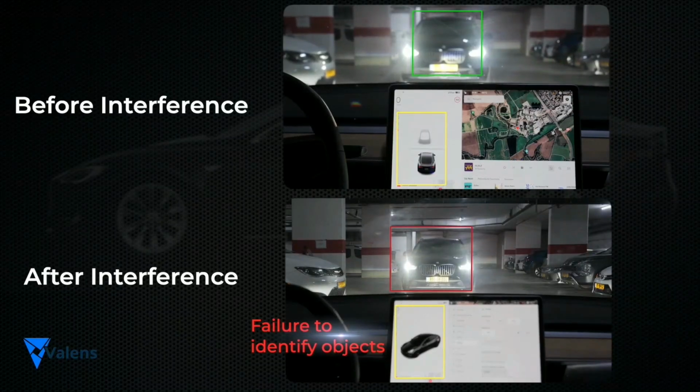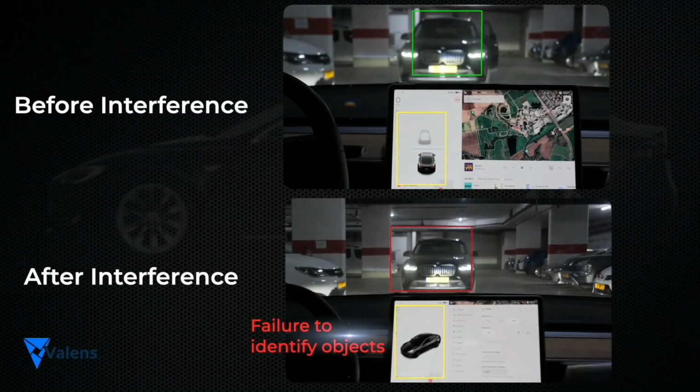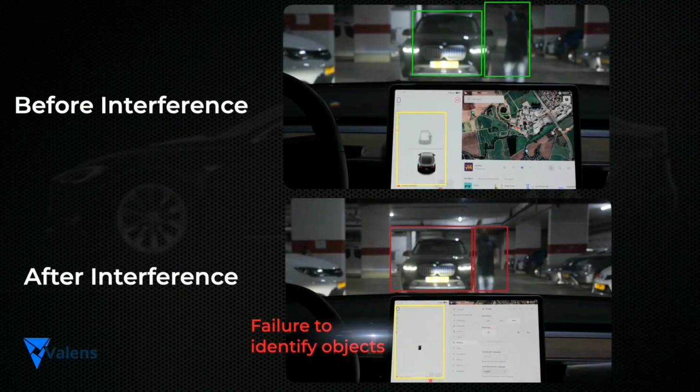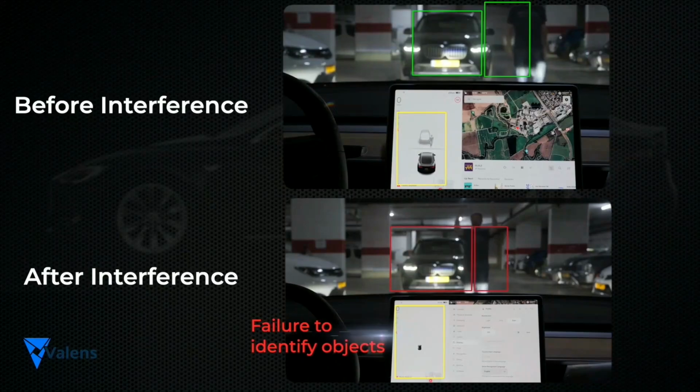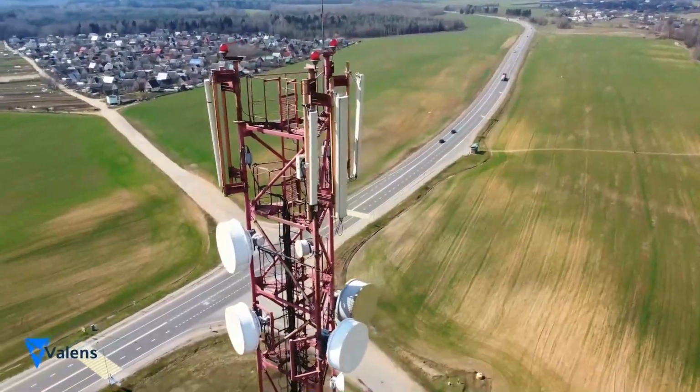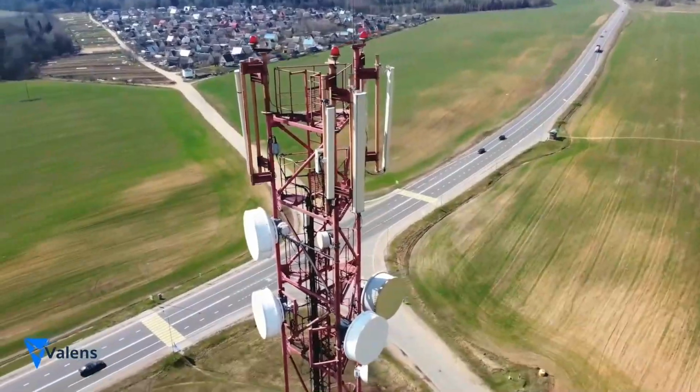In this case, the driver assistance system entered initial calibration mode, requiring a 30 to 40 kilometer drive to recalibrate, during which time the cameras were not functioning. It's important to note that the noises being applied here are noises that could occur on the road.